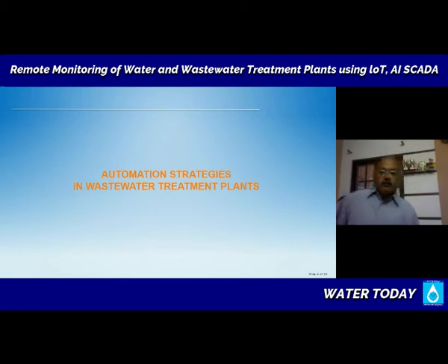Yeah, I have once again Sagaran from Vapi Industrial Effluent Treatment Plant. Yes, sir. Is there any color interference, because the effluent is having different color at different times? Will there be any issue on this matter? No, it is not. The color will interfere in optical systems. These are not optical at all. If you are measuring turbidity in an optical instrument, then the color can have an interference. But since these are not optical, these are high frequency ultrasound signals, color will absolutely have zero impact.